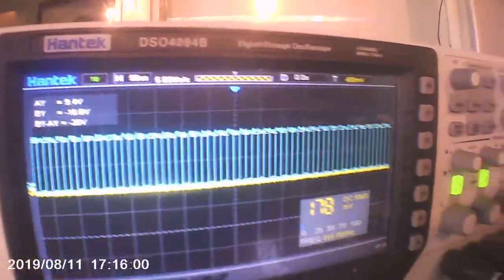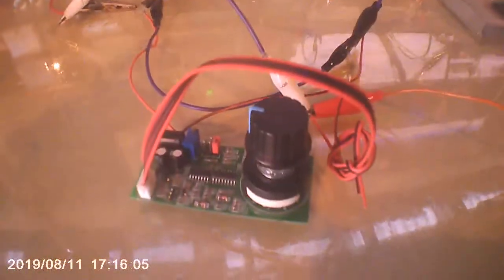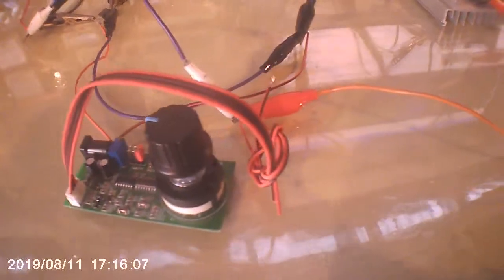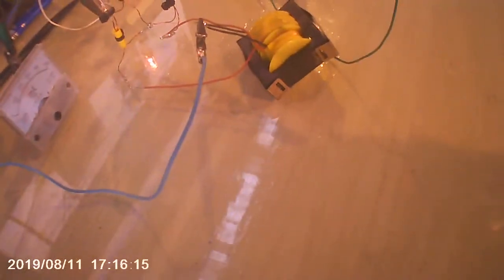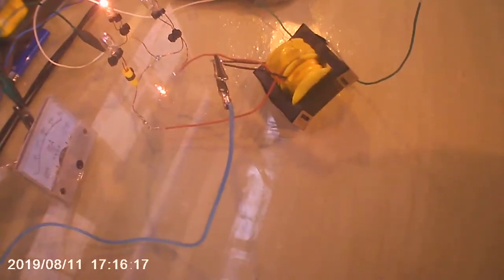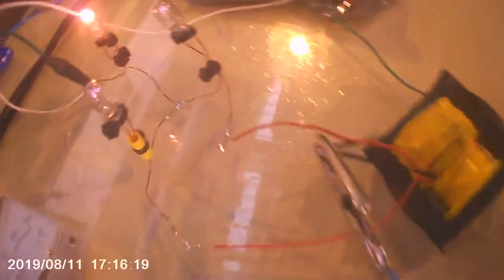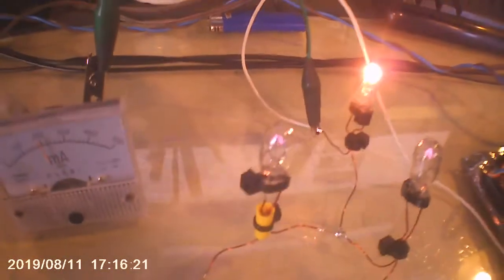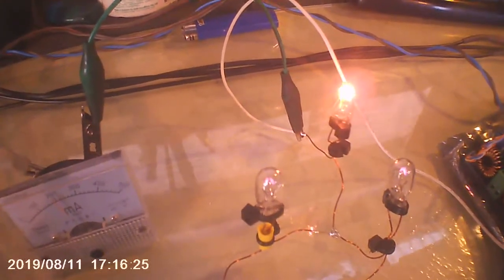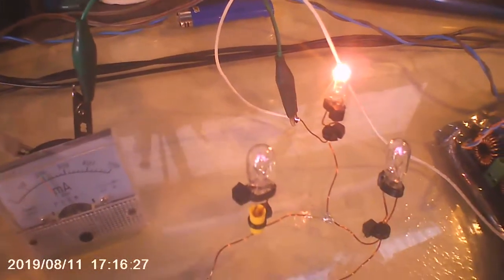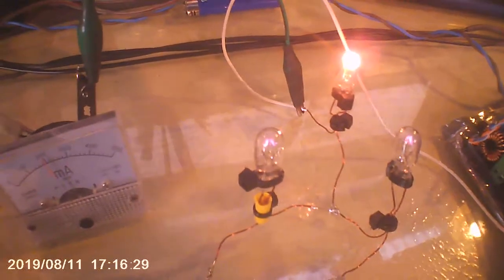Okay, I've just rerun that experiment with an off-the-shelf signal generator. It's clean enough, I think. I ran it with 10% duty cycle all the way up to 50% duty cycle, and that was the result I got all the way through the range, completely as you would expect. Yeah, no resonance behavior whatsoever. Does not work with square wave DC.